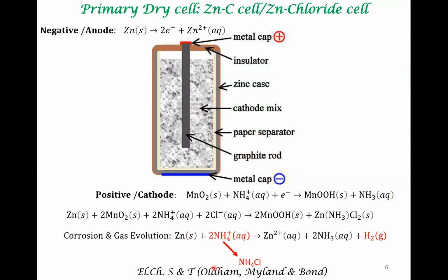And in addition, this particular component is mildly acidic. Typically when you have acidic substances, they give rise to corrosion. So you want to avoid very acidic media because many of the metals or metal oxides tend to get corroded in the presence of an acid. Even if it's a mild acid, even if you have pH 5 or so, the corrosion gets enhanced. So that's not very useful.